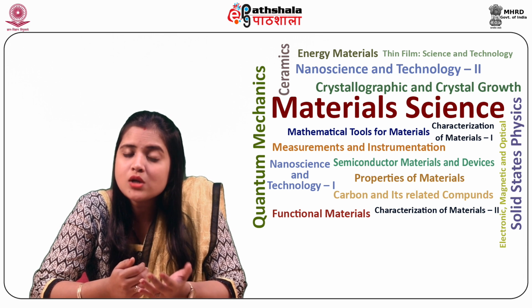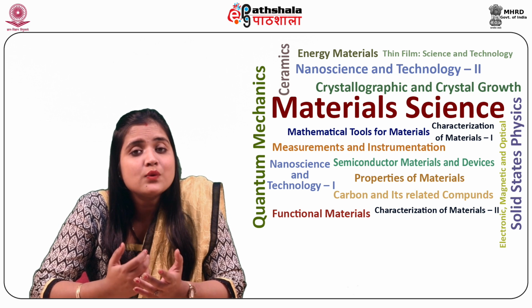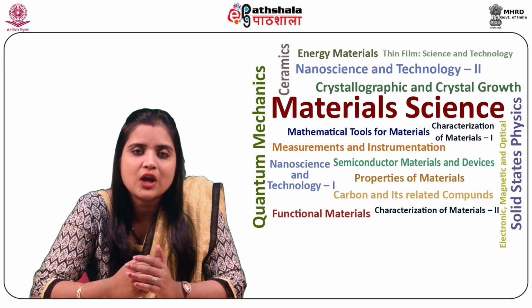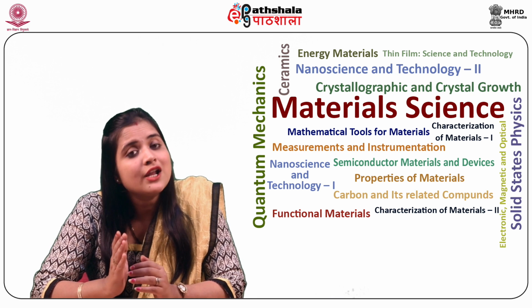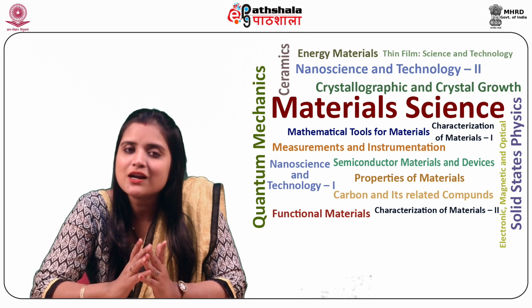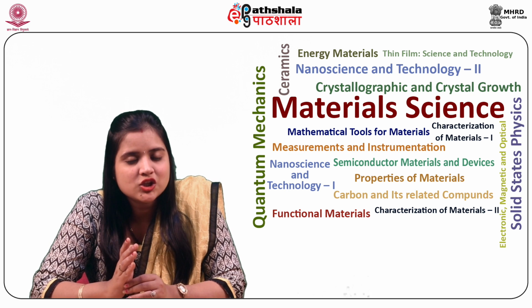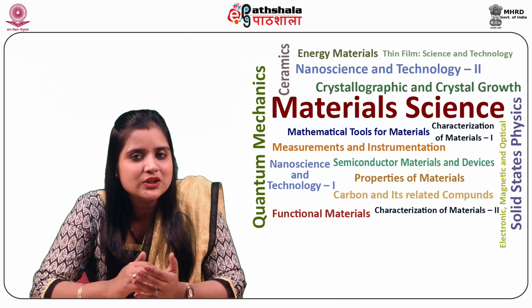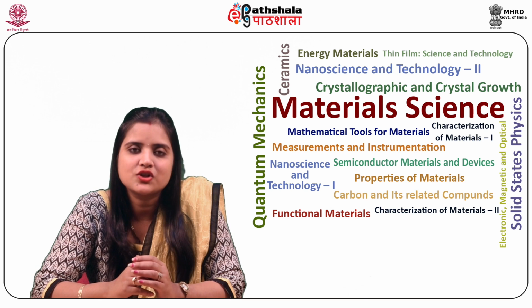Polarity of the Hall coefficient, that is the sign of RH, gives an indication of the type of majority charge carrier in a semiconductor. That is, if RH is positive, the material shows p-type conductivity. Otherwise, if RH is negative, the material possesses n-type conductivity, having electrons as the majority charge carriers.